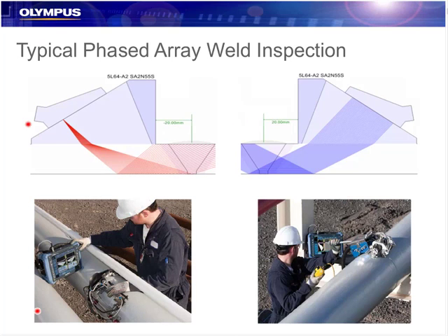So a lot of us in the last couple of years have become really familiar with phased array inspections. We're looking just at mainly weld inspection here. But typically when we use a portable OmniScan type unit or even an industrial type unit, we're using two types of inspection, usually a sectorial multi-angle scan or a linear or electronic scan where we use a fixed angle, number of elements, and fire to get that angle.